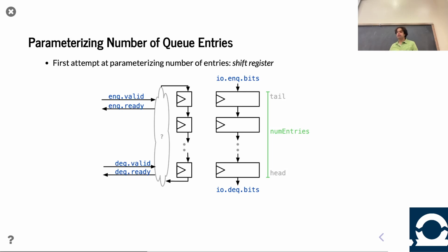It's not so much because it's asynchronous or synchronous. Even when perfectly synchronous, the issue is that data has to come in and go through all of the registers before it comes out. So it comes in, and there's no data coming behind me. There's going to be a bubble behind me immediately. And so with the bubble behind me, does this logic do the right thing, squeezing those bubbles out? So yeah, that's the concern.